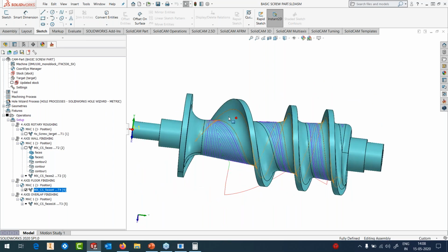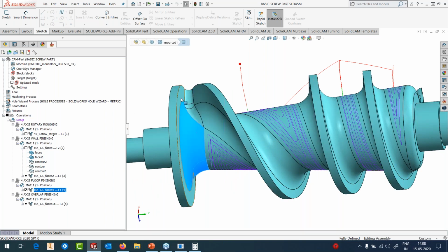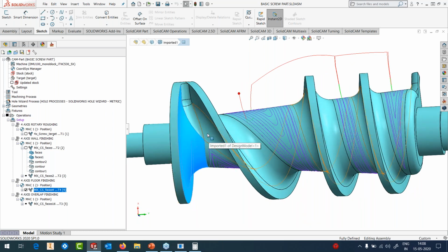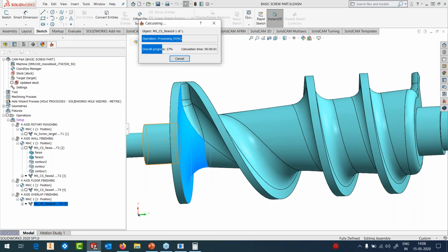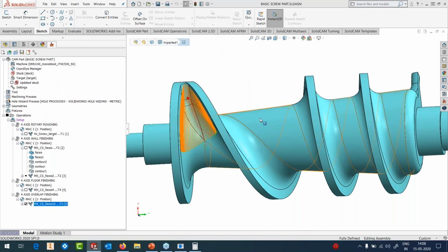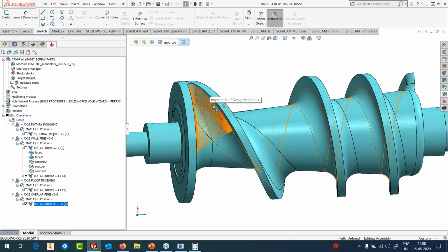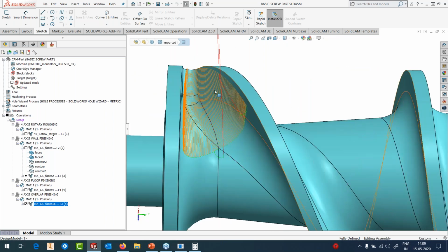And since I have toolpaths coming from this side, that is, this surface is one and this surface is another one, I have a region here which is not machined, because it's going and stopping since I'm using a pretty large cutter. So for that, I have created another toolpath here by defining a different kind of geometry. We call it an overlap toolpath, which overlaps between both of these toolpaths. And here it's using a smaller tool to make sure that it finishes that radius also. So this region I've done using this kind of toolpath. Again, this is coming from the generic toolpath functionality.